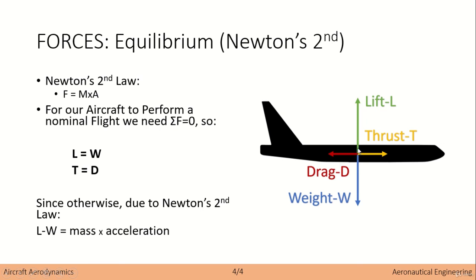But if we increase the thrust a bit more and continue to increase the velocity, then the lift is bigger than the weight, and therefore the aircraft starts to go upwards. So this is what happens. Of course, the thrust is usually bigger than the drag for these conditions, but in general, when we're in flight, the thrust will be considered to be equal to drag.